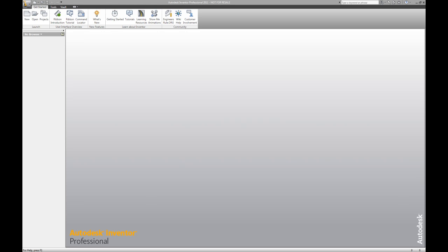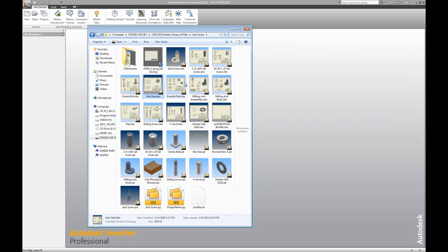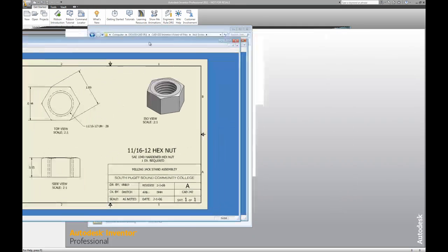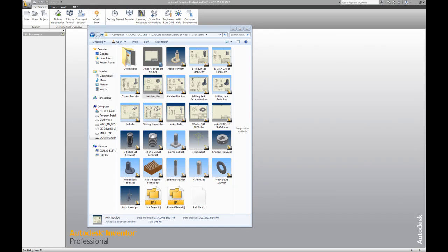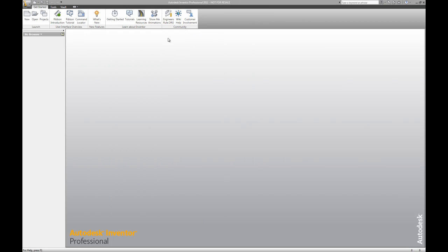And we're going to open up with Inventor View. I don't know if you know about Inventor View. Let me show that to you. So I'm going to go to the nut, right click, and go View with Inventor View, which is a little viewing program, sort of like Adobe. It's going to give me all of my dimensions that I need. So I'm going to park that over here. And there's a couple dimensions that are missing on that.